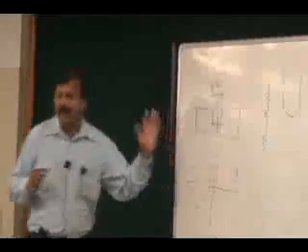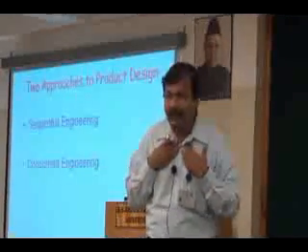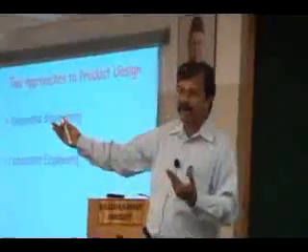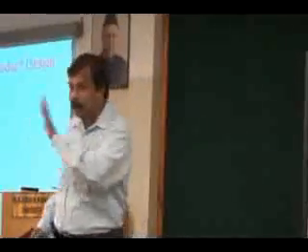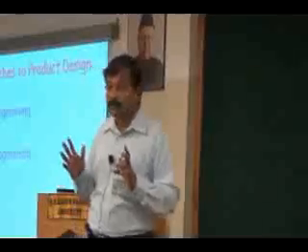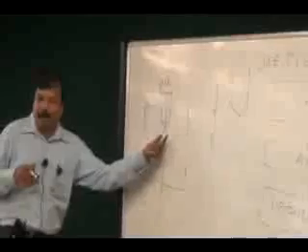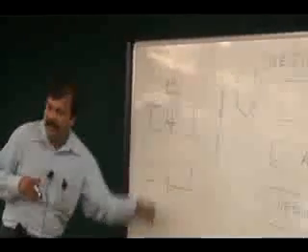As a manufacturing engineer, the first thing that I should say is, anything that you design can be made by me. And everything is associated with cost. Compare the cost of drilling with the cost of electrical discharge machining, and it will be at least 20 times more. Is it really worth it? Or can you make a small compromise? Permit a conical ending here or a through hole.